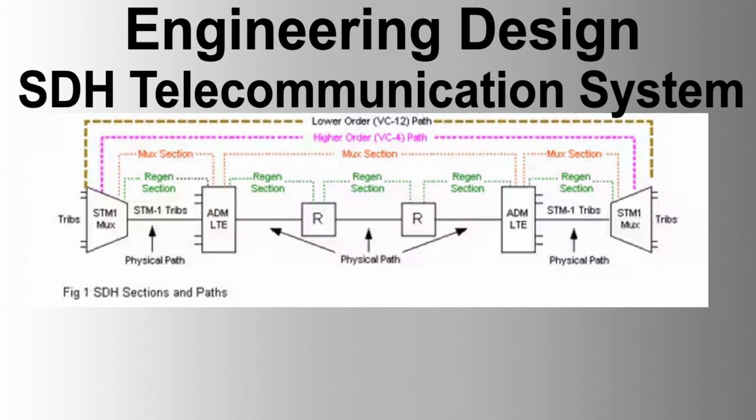The SDH design basis. Network design. Each SDH network shall comprise a 4x4 fiber-protected self-healing MS-SPRing system operating at STM16 2.488 Gbps. This ensures that the network can carry twice the traffic of a 2-fiber ring and provides protection against single failures.